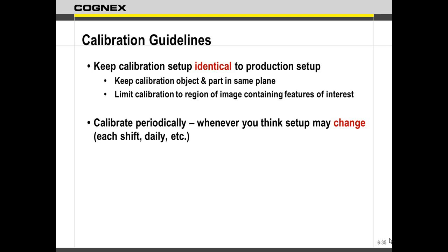Now, you might come to me and say, but 5 is kind of high. Could I do 1? I'm going to say it's completely dependent upon your application. In our application, we might be able to get away with 1, with what we're doing right now. But if I start adding a few more tools, that might get blown out of the water. So I have to think about, once again, adding these things on, because I have a fine patterns tool that then's controlling an edge tool, so those two are going to add together. That's what I have to think about. So I want to stay away from the camera's tolerance. I want mine at least above it, so I feel more comfortable with the measurement getting out of it.